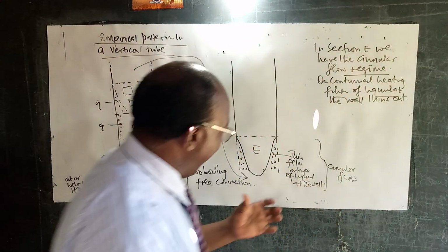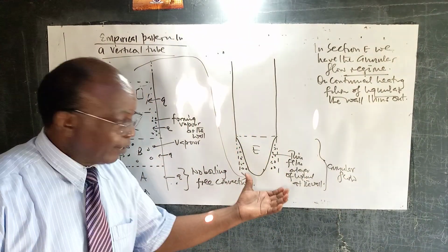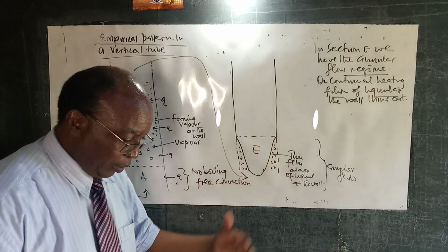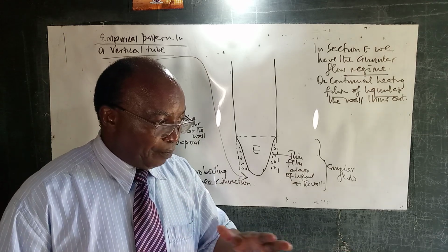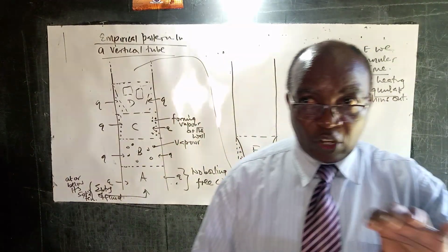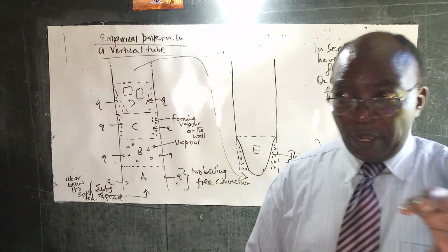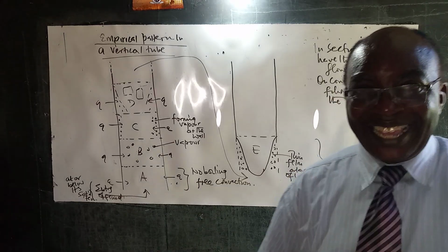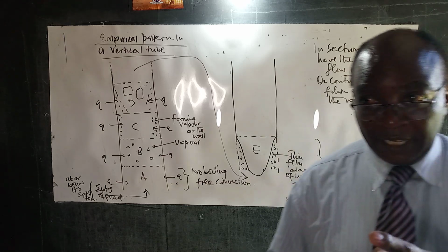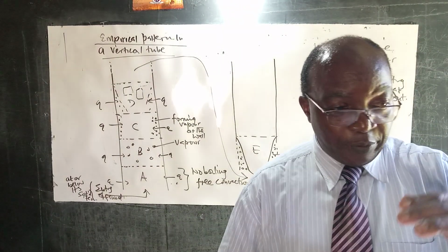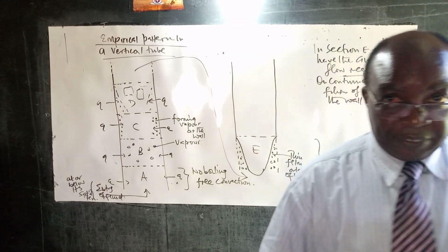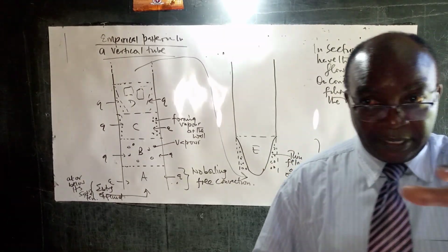When we are in the annular flow regime, as you continue heating, the film on the wall will continue being depleted. And when it's completely depleted so that the wall is no longer wet, we are going to have a sudden rise in temperature. Remember, when we talked about pool boiling, when we reached a certain critical heat flux, a vapor layer developed.